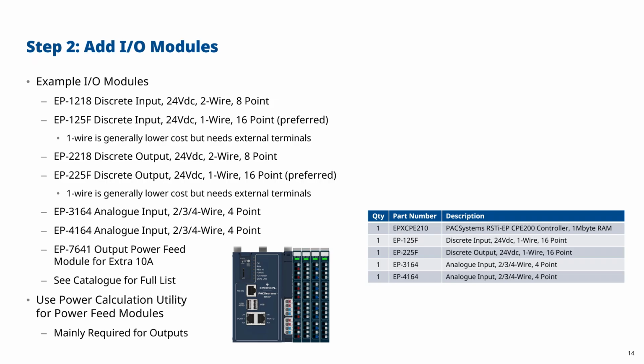I/O wiring. Again, there are some possibilities here for reducing panel space and for reduced third-party component cost. That's where the 2-wire terminals come in. But for many users, we would start with the 1-wire terminations if we're not sure. Another possibility would be to give 2 options on the quotation, one for 1 wire and one for 2-wire.